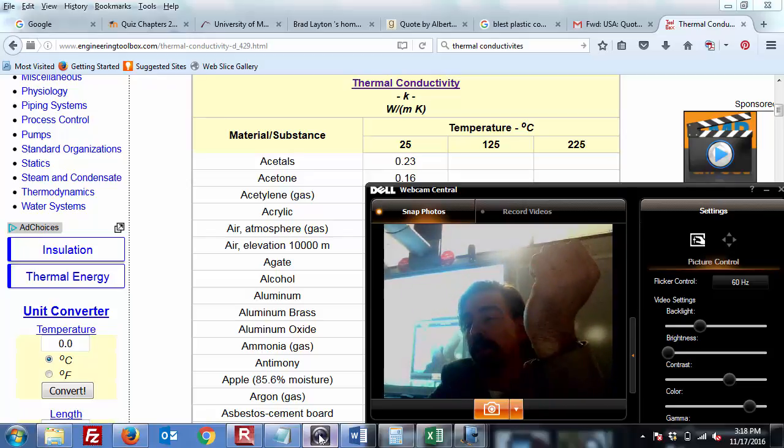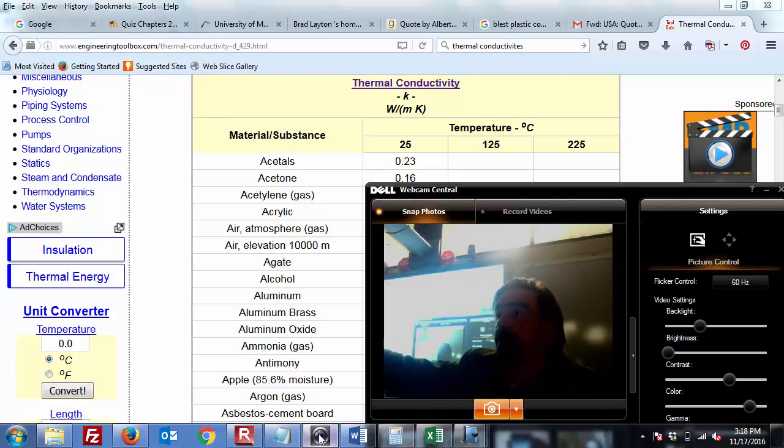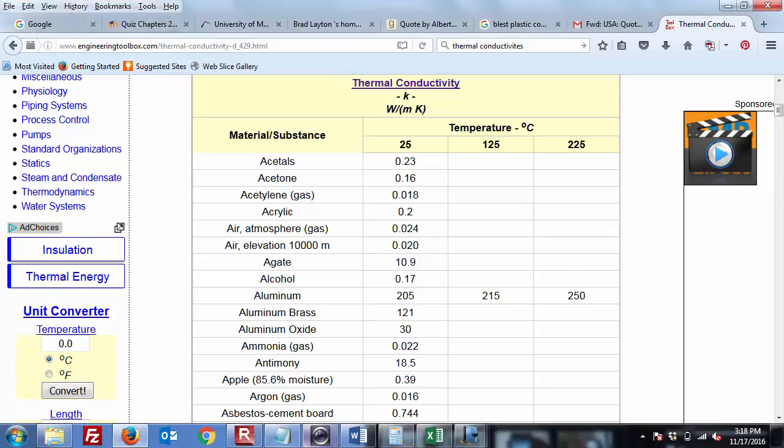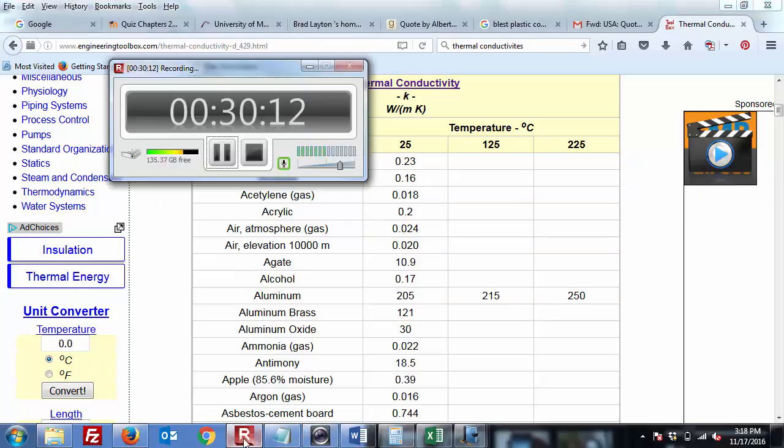It's pulling heat away from your hand faster than the other rock. It's just as simple as that. So the temperatures aren't different. It's the thermal conductivities. It's the same way that if you walked outside on a cold morning and the air was freezing, and say the water was very close to freezing, you would much rather have your hand in the air than in the water because the thermal conductivity of the water is much greater. It's pulling that heat away from you. So you're actually sensing the motion of heat flowing away, not just the actual temperature. Okay, let's take a little break there.